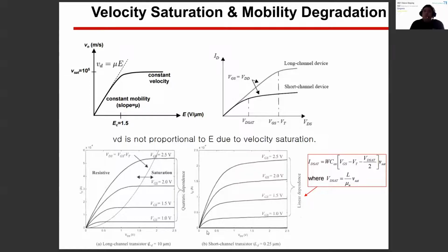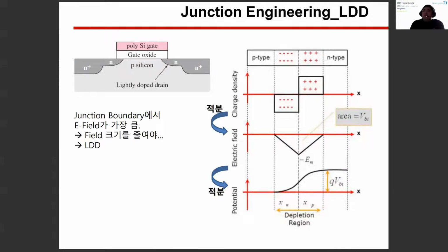This means that with velocity saturation introduced, more likely in short channel devices, the saturated current is lower than in longer channel devices, because the saturation of current, or the degradation of velocities, is introduced because of the electrons in the lattice.